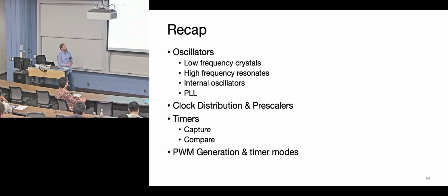We talked a little bit about clock distribution. It's good just to know that it exists when you're looking through CubeIDE and you want to push one of those clock values somewhere else. This typically happens when students are trying to interface with some weird hardware, like you're trying to make a VGA controller so that you can play images on a computer monitor. Or people have tried to do HDMI as well. That spec requires very specific timing, and it's easier if you get your clocks to the right value.